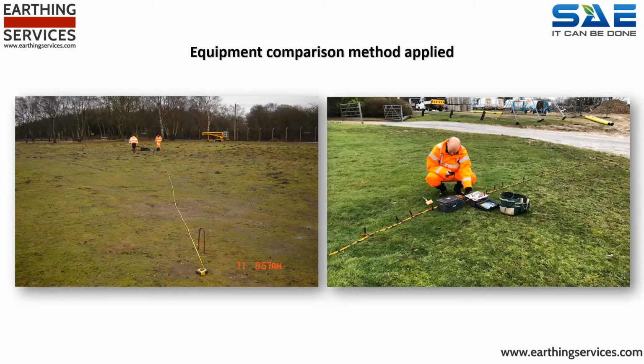Earthing Services has adopted the second method. Whilst it requires more equipment and establishment time, it is faster to complete and rules out any induction interference on the cables. This sort of test equipment takes a little time to manufacture, but the time saved on site and the confidence in the data it provides justifies the upfront time and equipment cost.